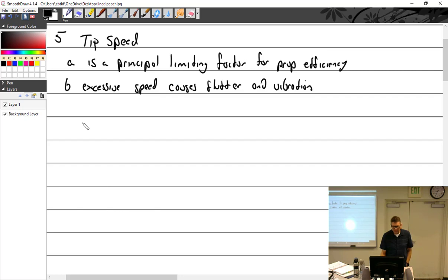Flutter is an unbelievable thing. I've got to find this video, I can't do it right now. But you talk about balancing control surfaces on aircraft. You guys had Phil, right? You probably talked about it. Okay, so you'll do more of that in second year. But it's critical to the balance, and it doesn't make sense. It's a fixed piece of aluminum or whatever, and you've got a rod going to it, and you think you can just make it go up and down, but yet it's got to be perfectly balanced. If it's not, it can get into this flutter.